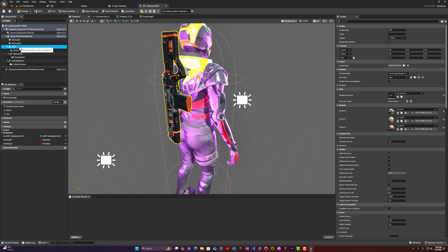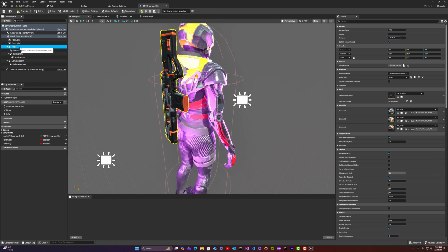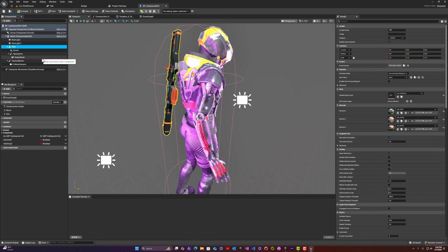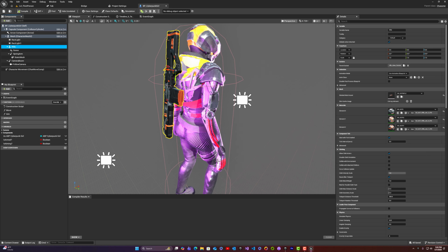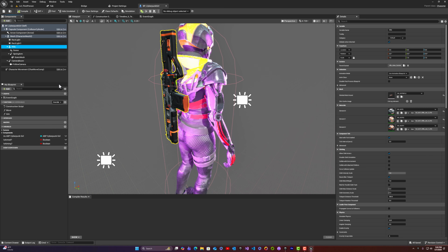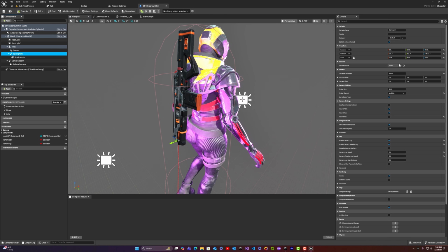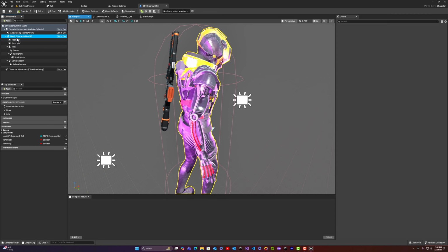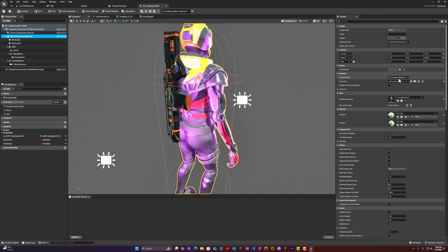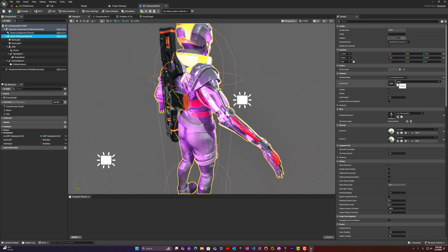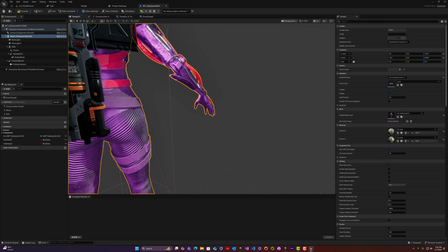And in script, at a certain point, I attach this component to another component, which is another socket on the body, namely a socket on the hand where the weapon is held. But to get my spring arm lined up with this, what I did is I took the character mesh out of its animation blueprint here for a moment, where it says animation mode, and chose use animation asset, and just found something where it was standing still.